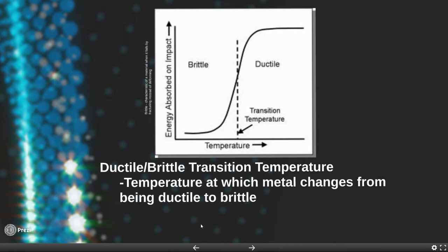Now you have to think, because if you originally plan for a metal to bend or be ductile, and then it's put into a very, very low temperature, it could change from being ductile to brittle, since now it's at a low temperature. And if you think something is going to be brittle and crack, when you put it in a higher temperature, then it's more ductile now.